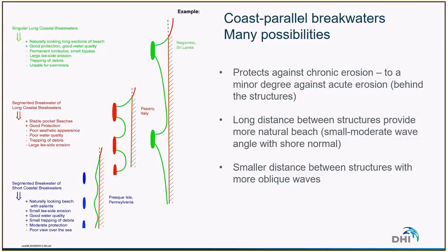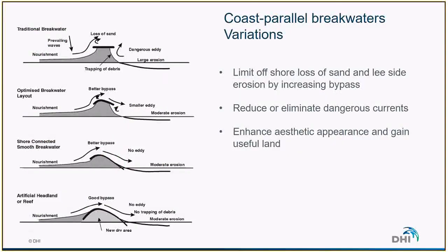Moreover, the breakwaters can trap sand on the coast with perpendicular wave approach, which is not the case for groins. So it has some advantages that the groins don't have. These variations aim at mitigating the disadvantages of the breakwaters by optimizing the shape of the structure.